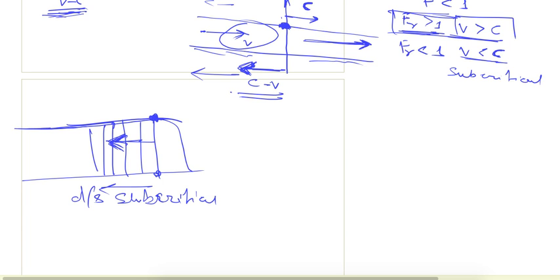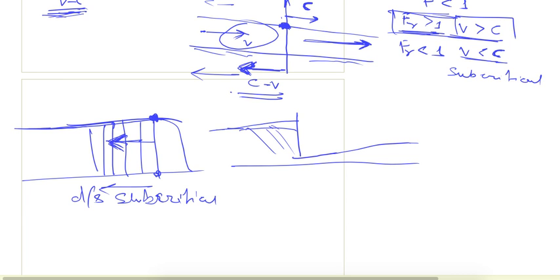And let's say if I'm putting a sluice gate here, we can say it will be rising on this side and it will be like this. So what we can see for both the cases here: on the upstream of this sluice gate, this flow is rising like this. Here it is a subcritical flow condition, so from here we can calculate our depths in this direction.